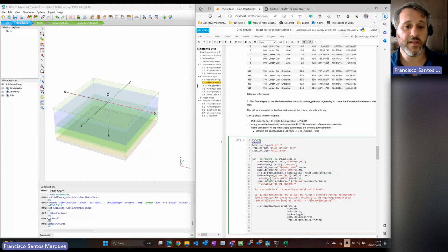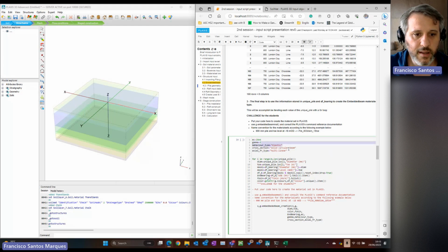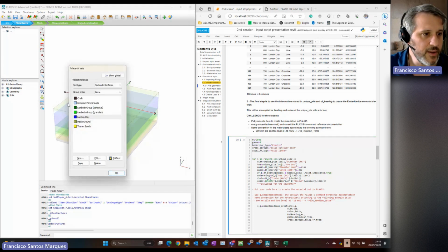because it's going to be 25 minus 20, since we are modeling it as a stick. In reality, there's going to be concrete in a place where soil is. So the 5 is just the difference between the unit weight of the concrete and the soil. The behavior is going to be elastic. The cross section size, maybe it's easy to show this.